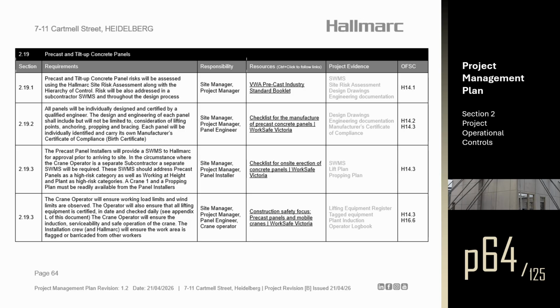The design and engineering of each panel shall include, but will not be limited to, consideration of lifting points, anchoring, propping and bracing. Each panel will be individually identified and carry its own manufacturer's certificate of compliance or birth certificate. Section 2.19.3. The precast panel installers will provide a SWMS to Hallmarc for approval prior to arriving to site. In the circumstance where the crane operator is a separate subcontractor, a separate SWMS will be required.